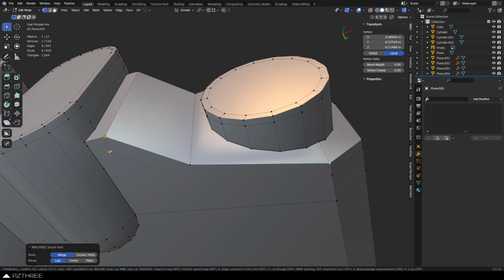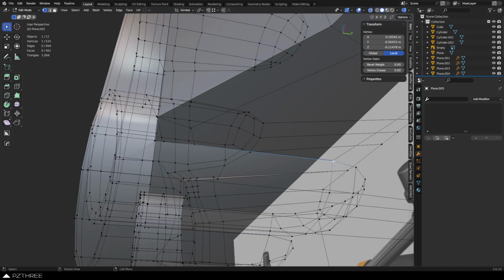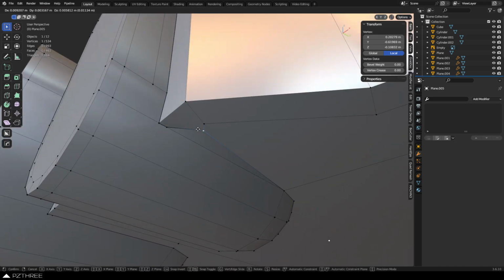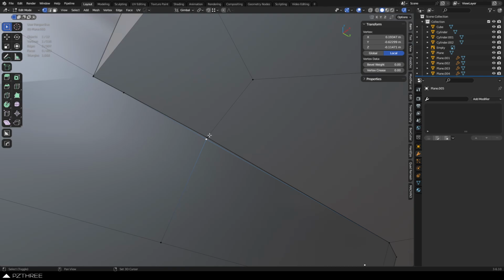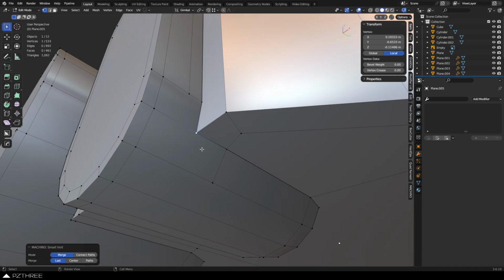It's just different workflows, right? You can do any of these whenever you want, really. You can see we got some doubles going on in here and some weird stuff like that. Sometimes you get an Alt-Z to just merge things. So some stuff like that could happen. You can see it's going to need a cut because it's going to create another vert there on that edge, and then we can merge it back up. And then all of this can go down to that edge, and there we go.